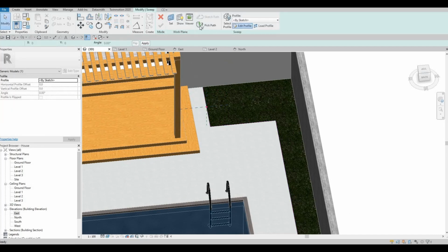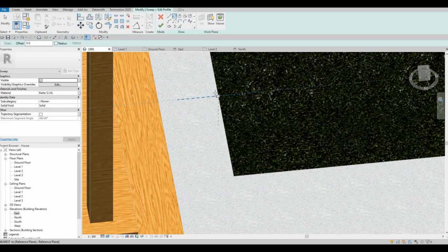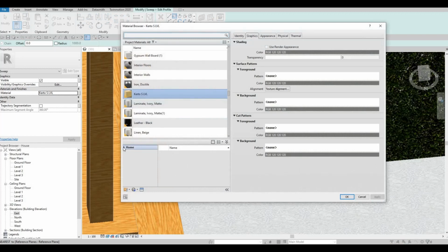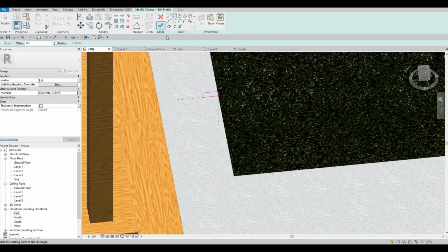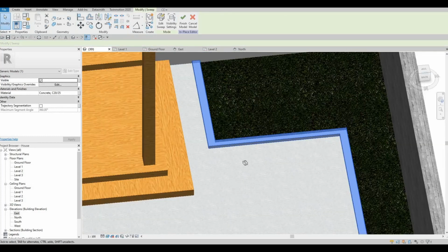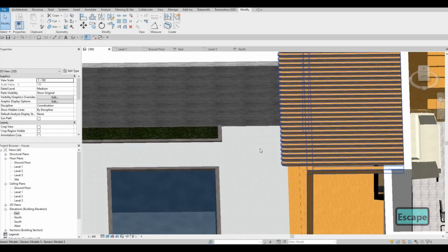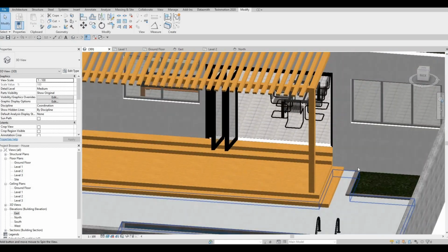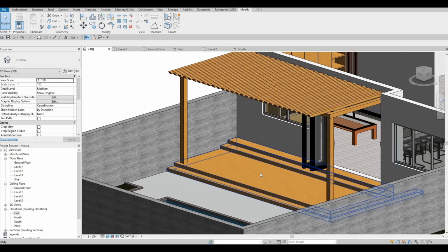So click on finish, edit profile, and then here we could select this rectangle, and we want to go and add it on this side, and then we want to change this to a concrete material. Anything will do. Apply, OK, and then OK again, and there you go. Something different that we could add to make everything look nice. Just a separation like that.